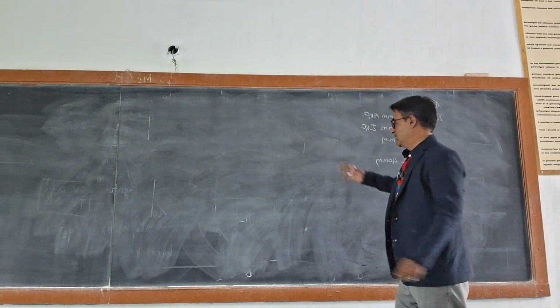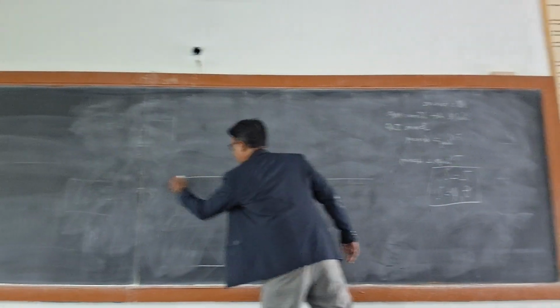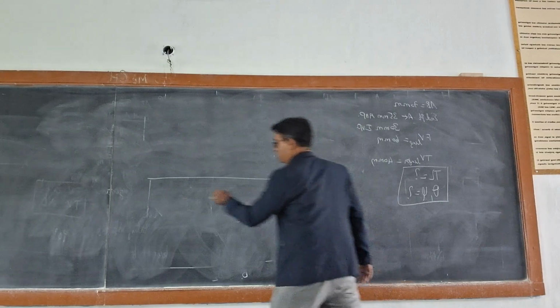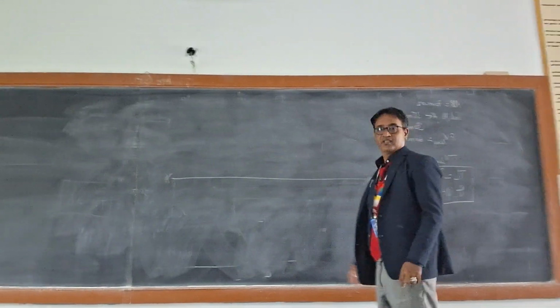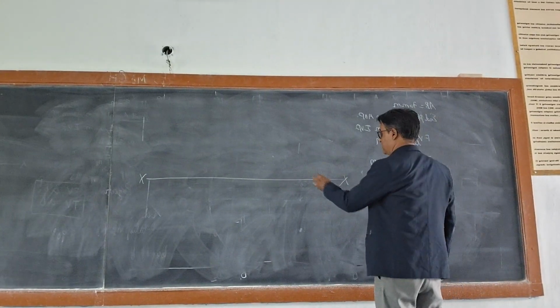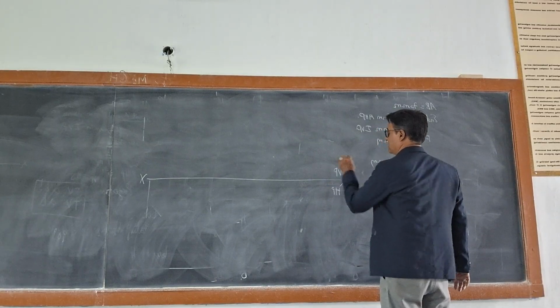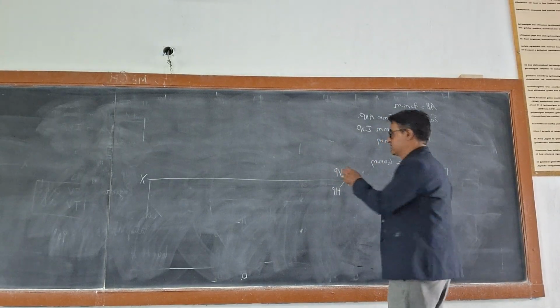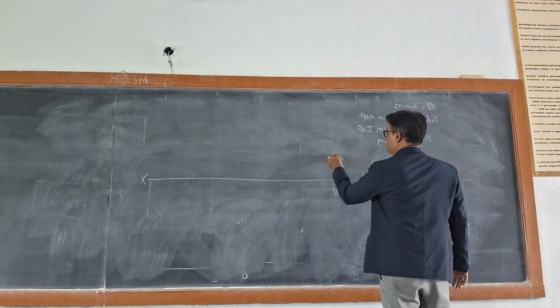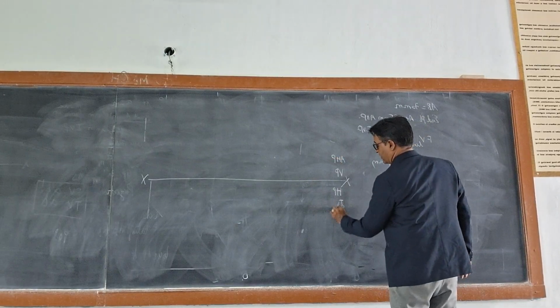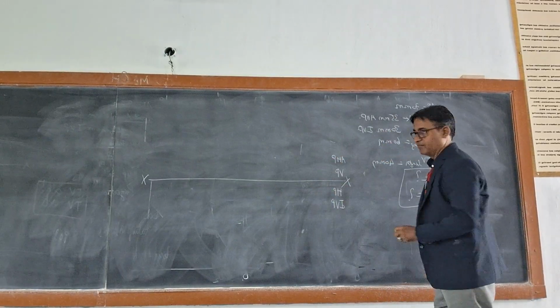So first I'll put down a format which you are going to follow for any straight line problem. Here you can see below xy will be HP, above will be VP. Distance above HP will be above XY, in front of VP will be below XY.